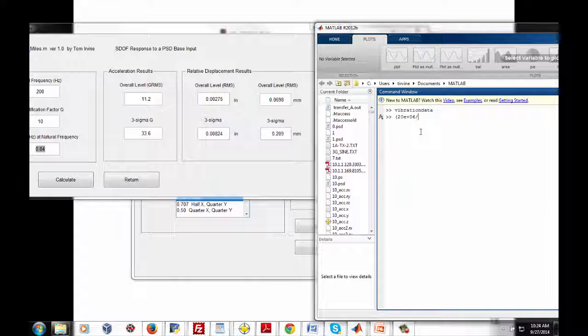what is going to be the duration? Well, we've got a natural frequency of 200 cycles per second, 200 hertz. So we can take cycles divided by cycles per second, and that will give us the duration in seconds. And what you have to remember here is that the response is not going to be pure sinusoidal. It's going to be narrowband random, but it's going to be narrowband random centered around 200 hertz. So we can, with a little bit of hand waving, assume that we can calculate the effective duration based on oscillations at 200 hertz.